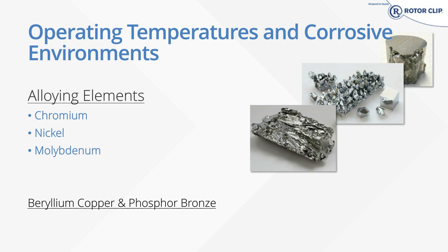The nickel increases ductility. This makes stainless steel easier to form. This also increases high temperature strength and corrosion resistance. This is particularly useful in industrial, marine, and chemical applications. And then finally, molybdenum, which increases corrosion resistance, adds strength at elevated temperatures, and expands the range of passivity for all parts. Moly also counteracts pitting, especially in chloride environments.